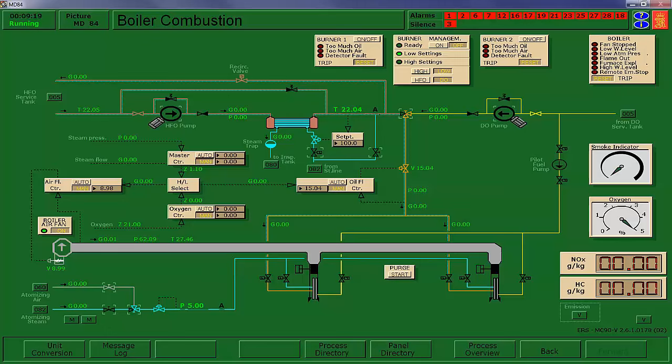Now, one of the advantages we have with this system is this has a pilot diesel oil pump that will pump oil through this, and then you have a second small burner here that has a spark igniter, and it ignites a small diesel flame that's used to ignite the main fire. Much better system than when you're trying to ignite the main body of the fire with an igniter like you do on a typical oil-fired boiler, say the one that we have on our steam sim.